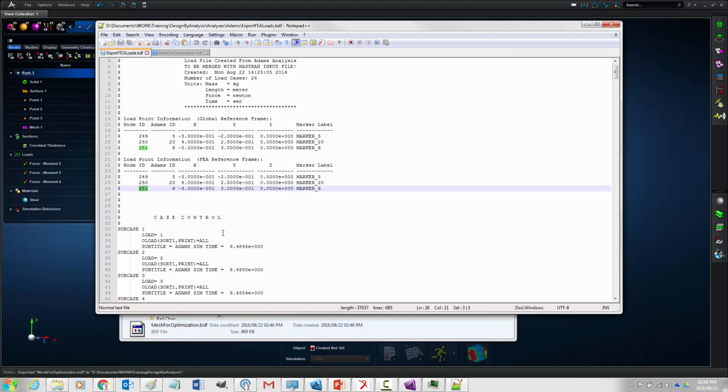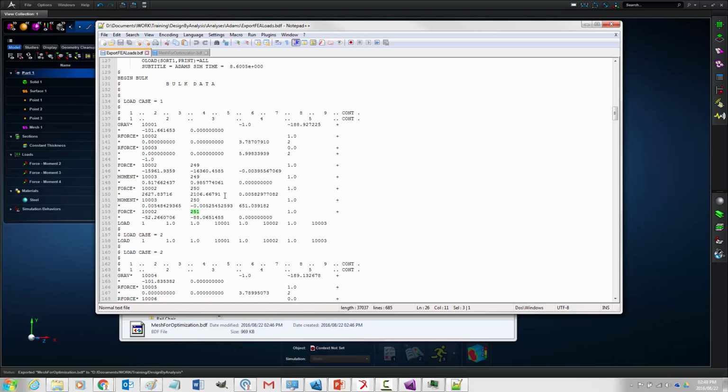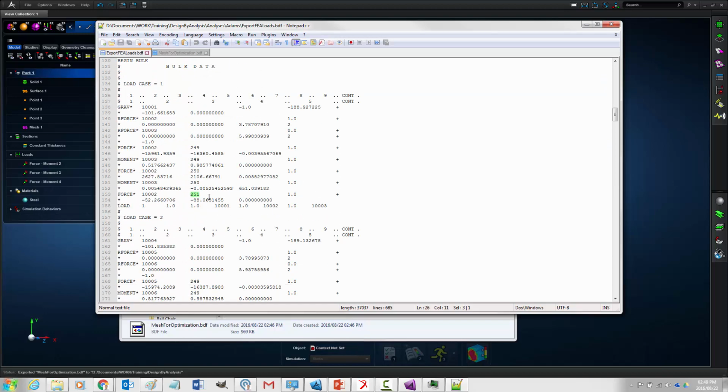The reason I don't want to edit the files is that the files are extremely sensitive to the location of numbers. These numbers are in specific blocks of data, and if you by accident delete a space and these numbers shift left or right, you might have a problem. So we're rather not going to edit these files if we don't really need to.